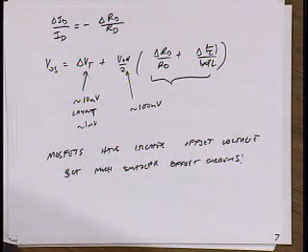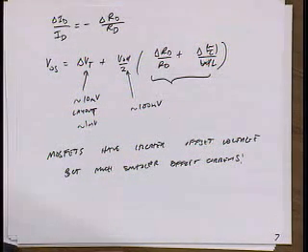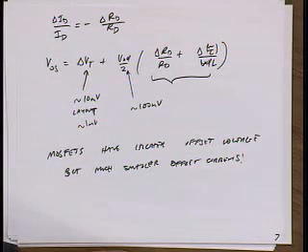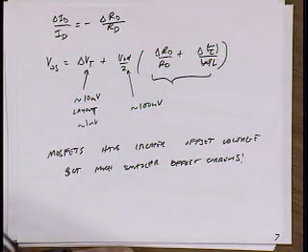A lot of circuits actually have systematic offsets, meaning that by design they are not perfectly symmetric. And if that's the case, there's going to be a systematic offset error. So you have actually a systematic offset plus a random offset, and both come into play. Okay? Now, most circuits that we design, the systematic offset is very small.